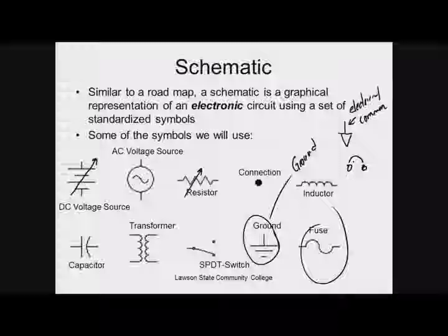So that's one big advantage that AC has over DC, is AC has a tendency to self-extinguish because it drops to 0 volts. So when it changes direction, it literally drops to 0 volts. If it drops to 0 volts, we have no push. So AC is considered to be self-extinguishing. DC, we have to do things to try to prevent them from arcing. We break contacts extremely fast, or we put a special circuit on it called snubber circuits and stuff like that.